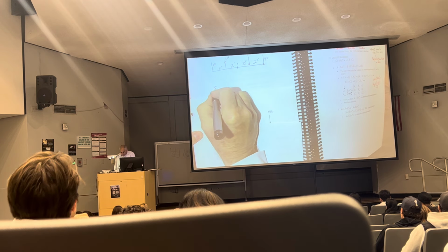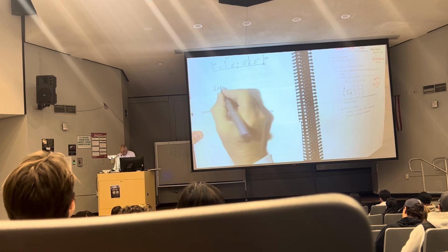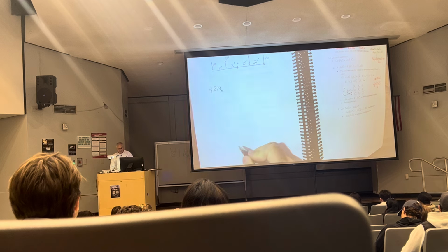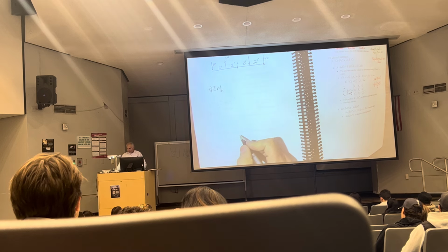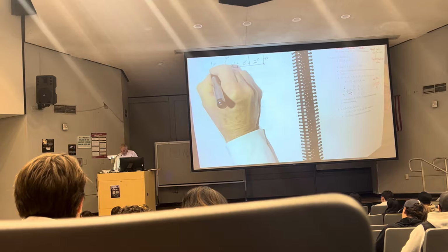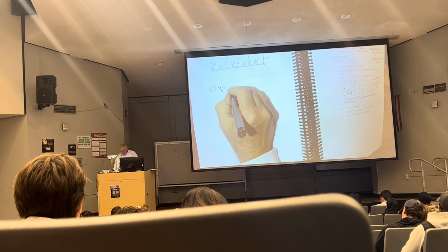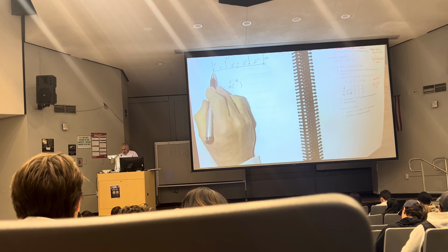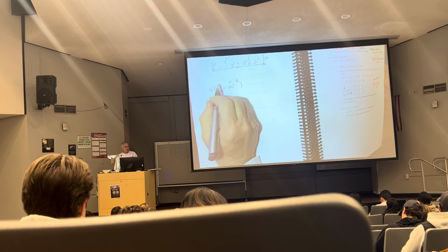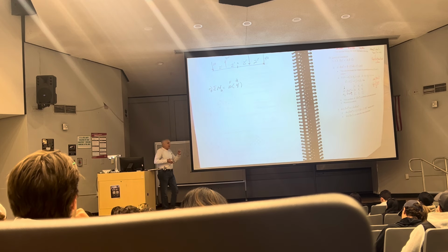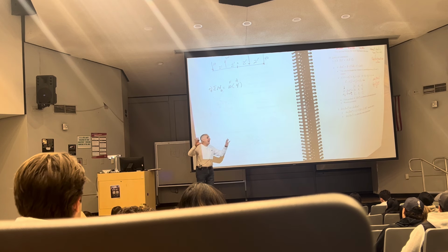So I'm going to say sum moments about O, and I'm going to take clockwise first. You with me? So let's go with this one first. 10, that's the force. What's the distance from 10 to O perpendicular wise? 4. That's how simple it is. 10 times 4 gives me the magnitude of the moment.